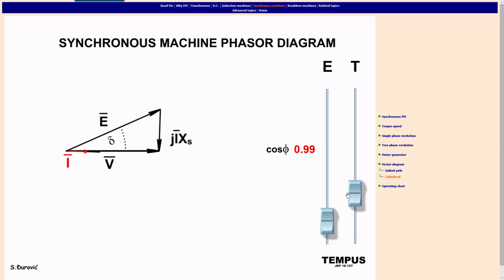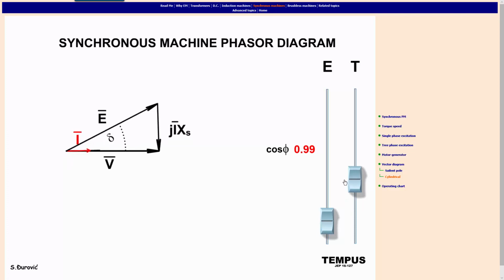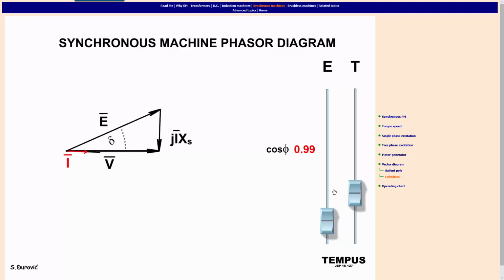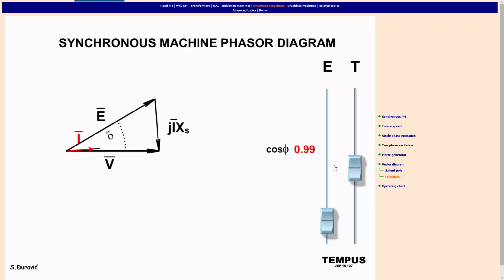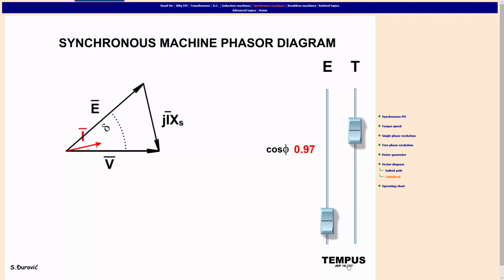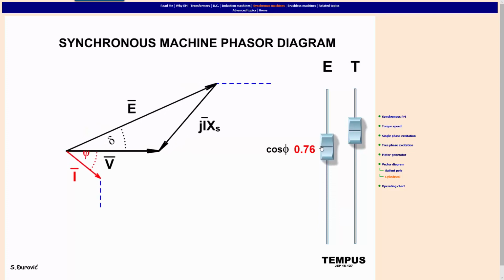Machine generates more electrical output power, and you see it was lagging, and then after generating higher active output, machine goes under capacitive region. There is a side effect. When you change generated active power, there is a slight change in reactive power. But that power change can be corrected by field current. Here you see.